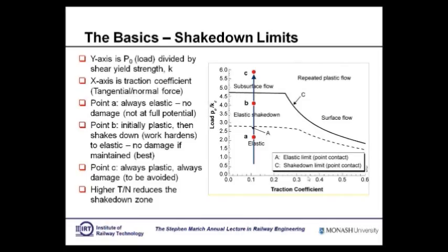Doesn't matter what you do to it, it'll keep on going if you're in this regime. Now, this region here is the beautiful one. This is the challenge, because what happens in that region, called the elastic shakedown, is that you actually do work harden the material a little bit, and so you are squeezing it, but you're controlling that work hardening process. So you're making the material better, but you're not destroying the material. So the objective is really to be in this zone here.